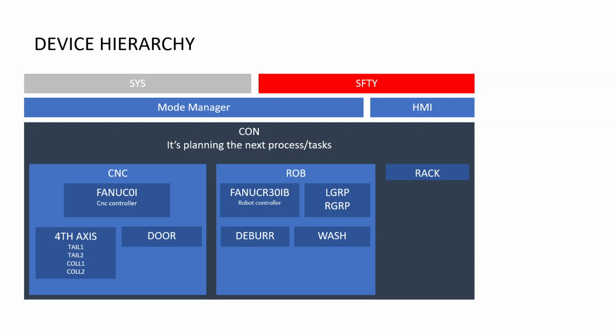I think in future iterations of this work cell, the fourth axis controls will be housed inside of the FANUC 0i CNC controller, because I believe the idea is to move the valve hardware that we have on the SMC and roll that into valve hardware that's tied directly to the CNC controller and is only accessed from the CNC controller, and must be requested by the PLC to the CNC controller to turn on the tailstock or extend it or retract.